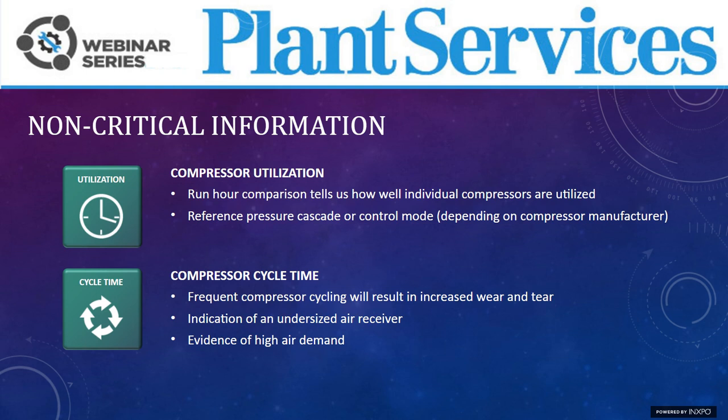Let's take another look at compressor utilization. It's another important value, in particular for multi-unit installations or multi-unit stations with same-sized equipment. The run-hour offset is a benchmark for how well each individual compressor is utilized, for instance by controlling a compressor station using a higher level controller.